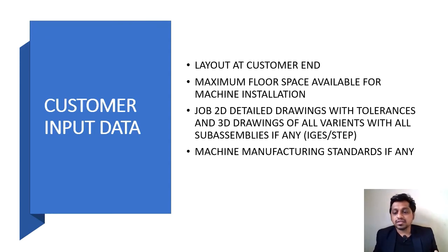We have a layout at the customer end. This is a very important factor, because customers have different layouts, different locations at which the machine will be placed, right? So we should know the space available for the machine, because sometimes it might happen that our machine will not fit into their layout. So it is very important to ask the customer for their layouts, how much space is available and all those things. The maximum floor space available for the machine installation is an important factor that we should consider.